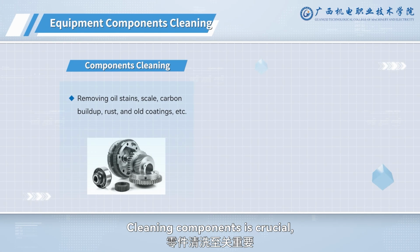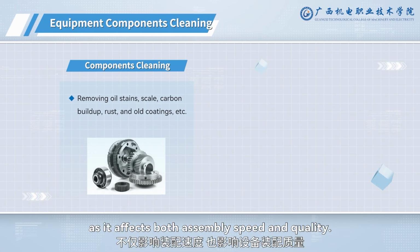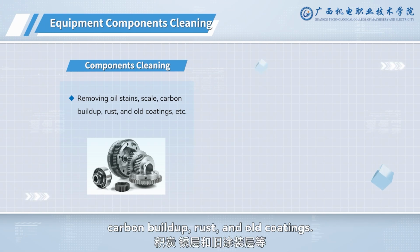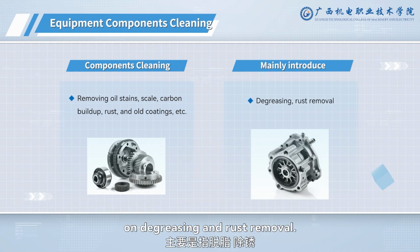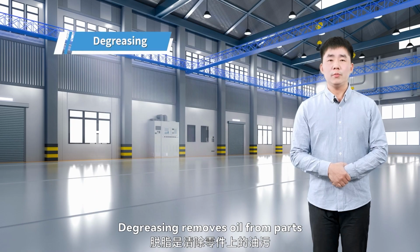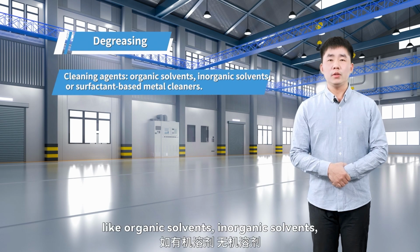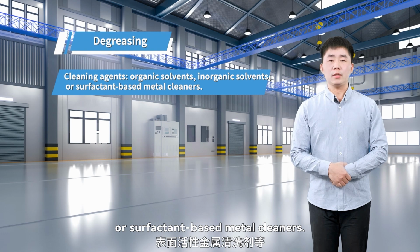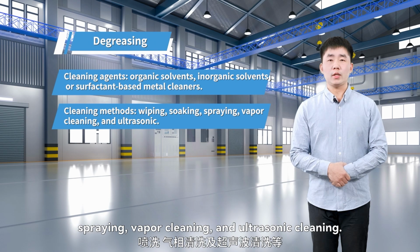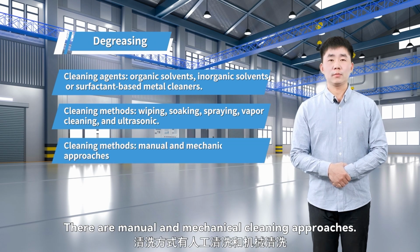Cleaning components is crucial as it affects both assembly speed and quality. Cleaning includes removing oil stains, scale, carbon buildup, rust, and old coatings. This course focuses on degreasing and rust removal. Degreasing removes oil from parts using cleaning agents like organic solvents, inorganic solvents, or surfactant-based metal cleaners. Cleaning methods include wiping, soaking, spraying, vapor cleaning, and ultrasonic cleaning. There are manual and mechanical cleaning approaches.